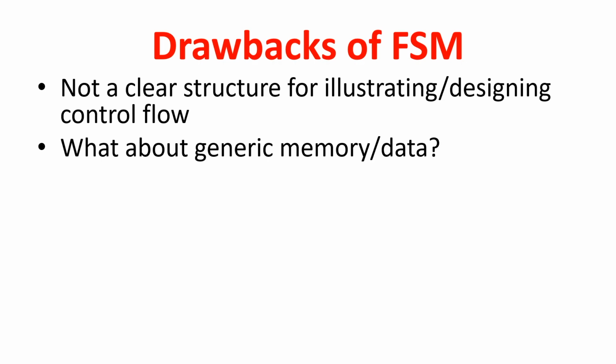And what about generic memory or data? Suppose you take a 64-bit memory or 64-bit register. We can model a 64-bit register using FSM, but whenever you want to design an FSM for a 64-bit register, how many states will be there? 2 to the power 64. We will not be able to tabulate or draw the FSM for a 64-bit register.